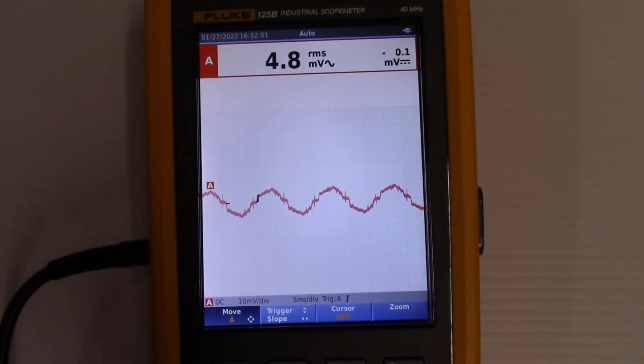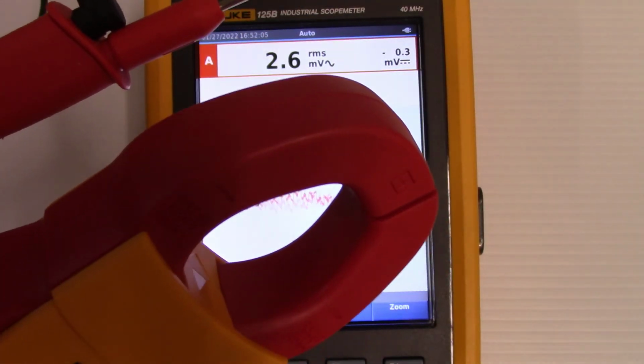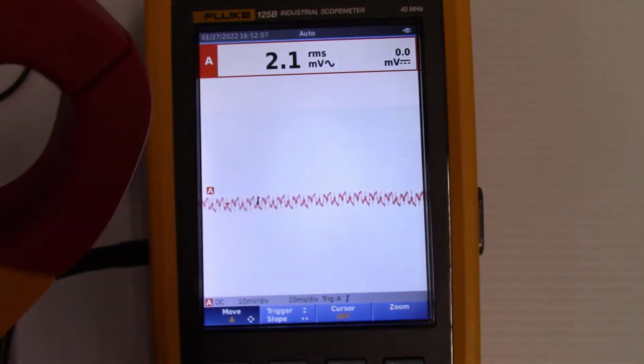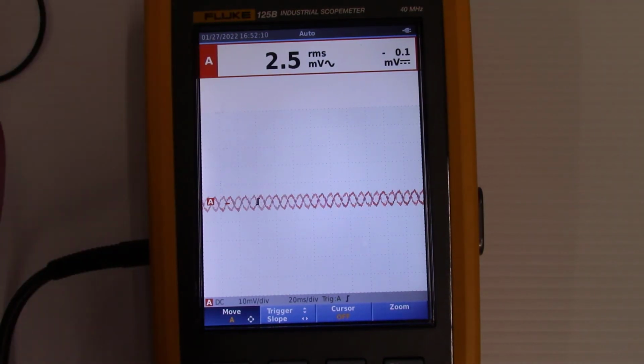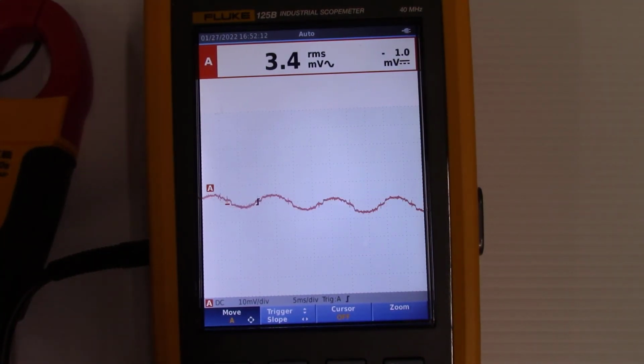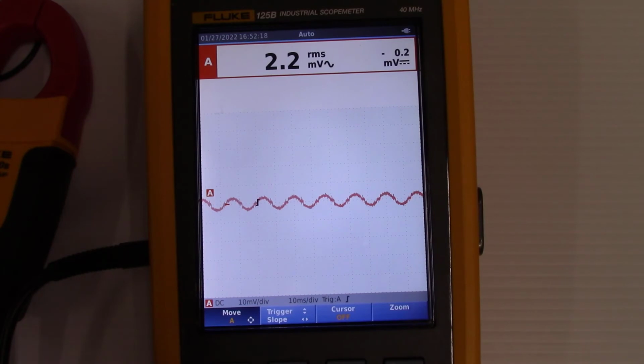So, things to think about. Number 1, polarity with respect to each other, and I'll show you what happens when you miss that. It's very, very important when you're working with 3-phase power equipment. You may have 3 voltage probes and 3 current probes. You need to make sure they're all polarized correctly, okay?